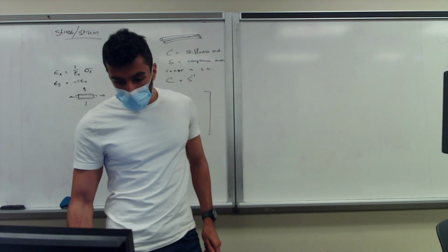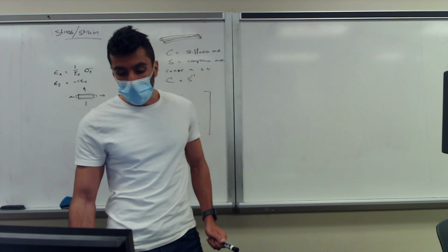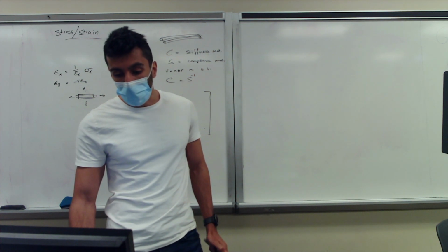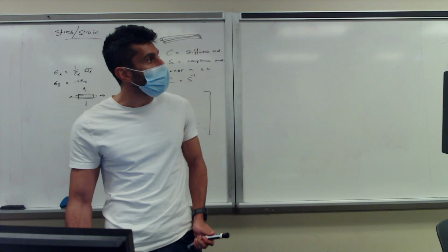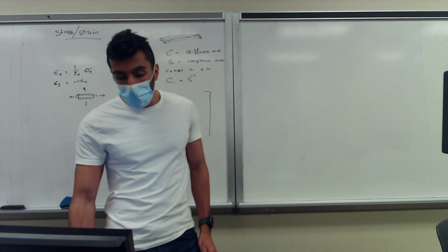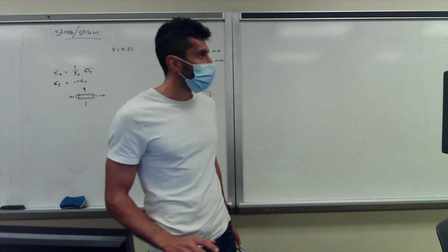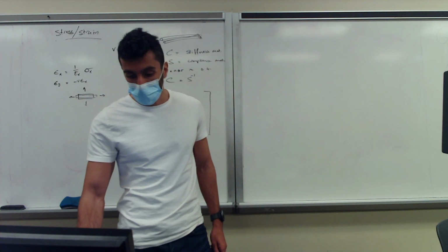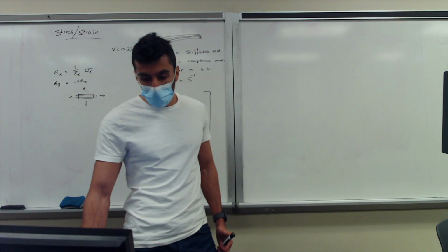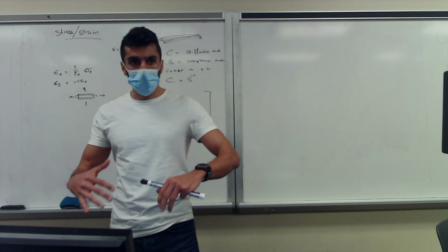Again, there's also Hooke's law for shear. In this case, tau is equal to G times gamma, where the shear modulus for isotropic material is given as E over 2 times (1 plus the Poisson ratio). We have no Poisson effect, no temperature effect, therefore the generalized Hooke's law is just given as is. They're much simpler. And this will be our complete set of equations. We skipped that during the initial part of the lecture, so that's already a bit of Hooke's law.